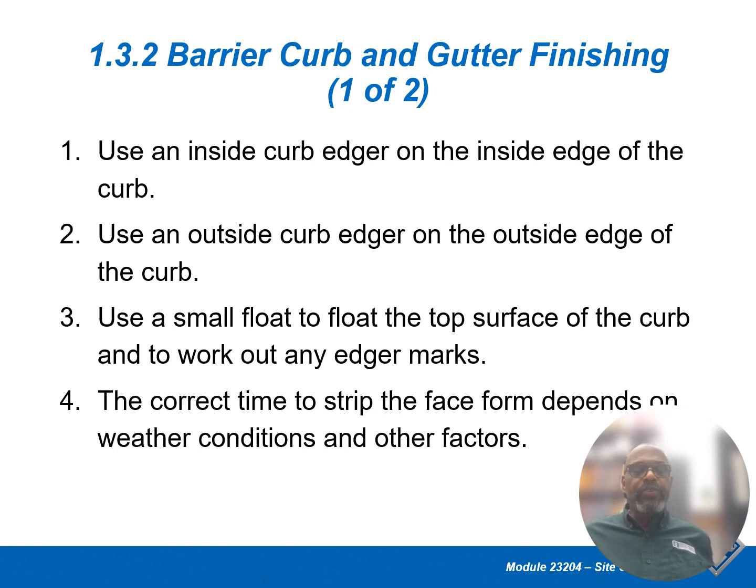You saw that form. That form is basically giving you the shape of that curb or the gutter. Once you set it in place, resting on the top and resting on the bottom of the form, you will be able to use it to design that shape that you're looking to have.